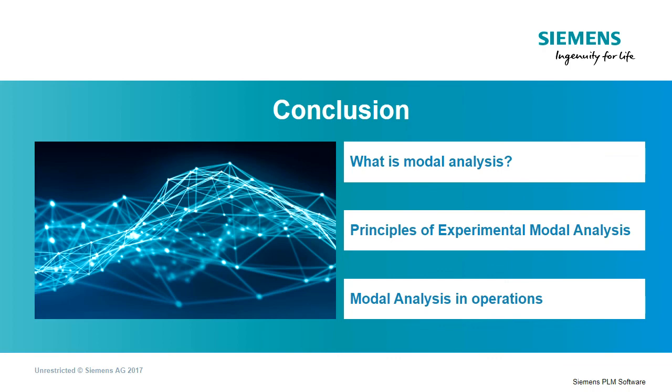Finally, we got a quick glimpse at the methods available to identify a modal model in operating conditions, where the forces acting on the structure cannot be measured and thus frequency response functions cannot be obtained.